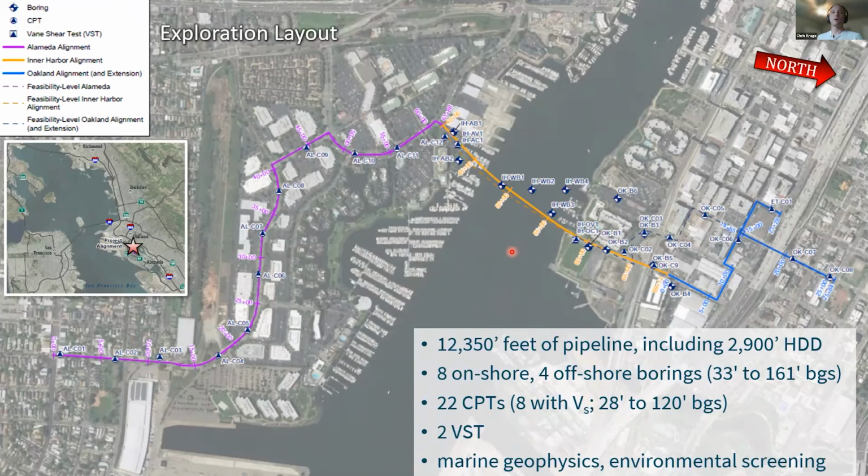And so the exploration program was rather extensive. It consisted of 8 onshore and 4 offshore borings, 22 CPTs, 8 of which with seismic readings, a couple of vane shear tests, as well as some marine geophysics and environmental screening work.